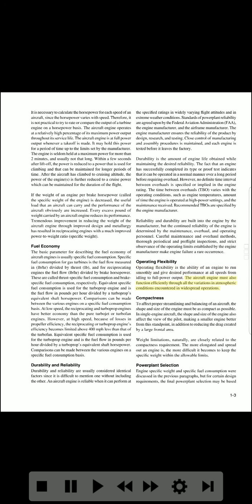The aircraft engine must also function efficiently through all the variations in atmospheric conditions encountered in widespread operations. Compactness. To effect proper streamlining and balancing of an aircraft, the shape and size of the engine must be as compact as possible. In single-engine aircraft, the shape and size of the engine also affect the view of the pilot, making a smaller engine better from this standpoint, in addition to reducing the drag created by a large frontal area. Weight limitations, naturally, are closely related to the compactness requirement. The more elongated and spread out an engine is, the more difficult it becomes to keep the specific weight within